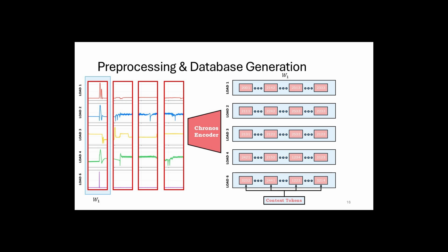to use. From this downsampling, we implement a sliding window of 250 data points, which is around half a second, with a stride of 50 steps over, which is about 0.1 seconds. And then from this extraction, we encode that using a transformer-based encoder, which is pre-trained on time series data. And how we do the actual windowing is we define a window here as 250, and we stride it over. So we move it over the signals here in order to extract that information.